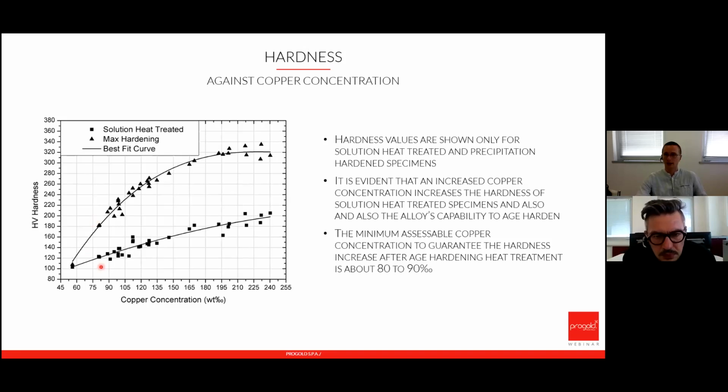Talking about 18 karat, there is no other way to make the alloy harder than copper concentration. Obviously, if you use a wrought alloy, you can deform it to increase the hardness, but it's not every time a useful solution, because sometimes you just have to cast and then do an edge hardening. So in this case, the copper and the grain refiner will help you. I just want to say that also a small grain size could help the mechanical properties, hardness also.